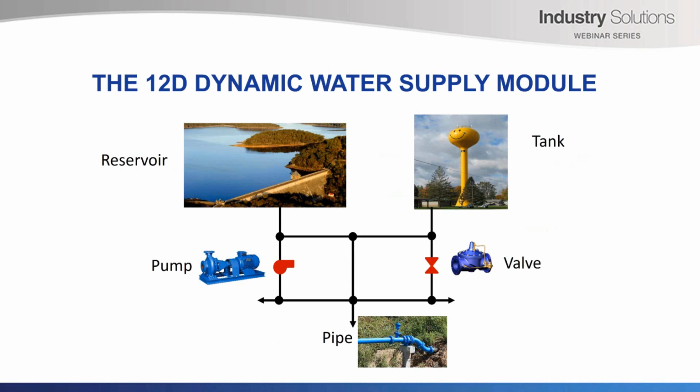Okay, so our nodes are sources of inflow or outflow from the network. So we have reservoirs and tanks, essentially the same thing, except a reservoir is an infinite supply of water at a predominantly constant head. A tank adjusts the head in the network depending on the hydraulic conditions. So the tank will empty and fill subject to different hydraulic constraints. Okay, so our network must contain at least one tank or reservoir, and it must contain at least one pipe. Other than that, no restraints.